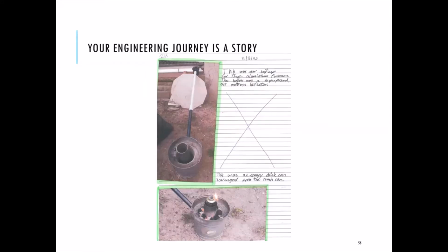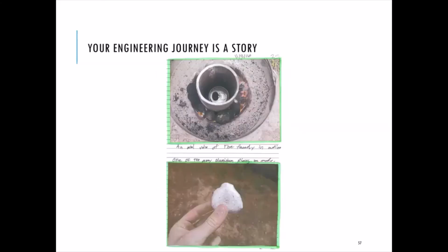And then one of the students recognized that we didn't have a lot of money because we're a brand new team, so it might be difficult for us to buy some of the parts we needed. So then they looked into building their own foundry, so that we could take soda cans that we found on campus at the school, melt them down, and eventually turn those metal ingots and cast them into parts for the robot.